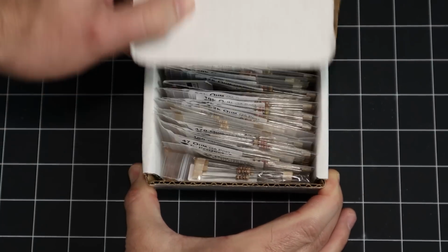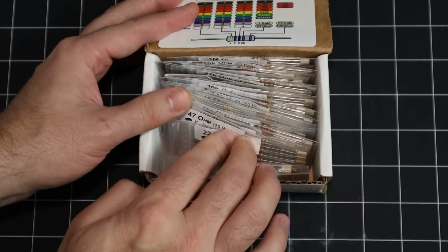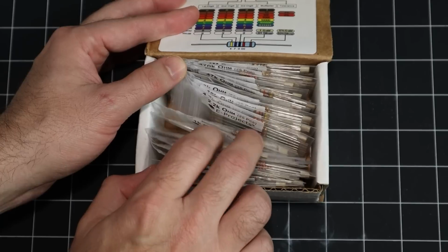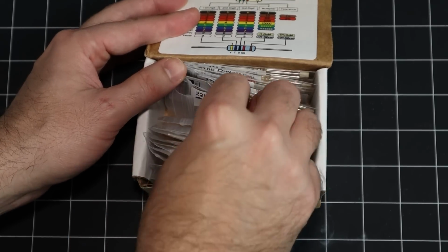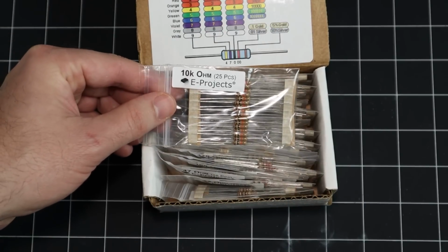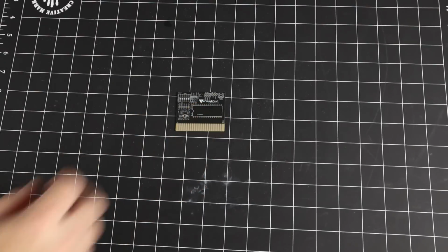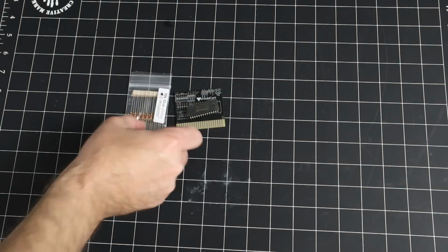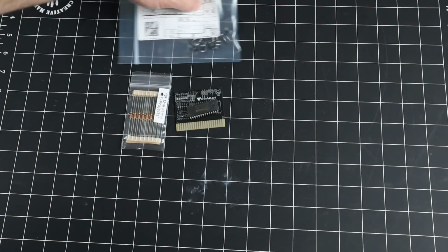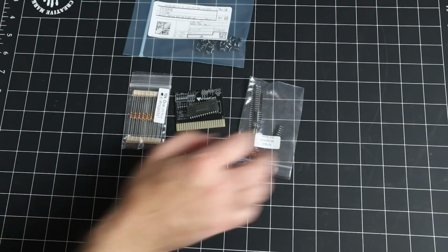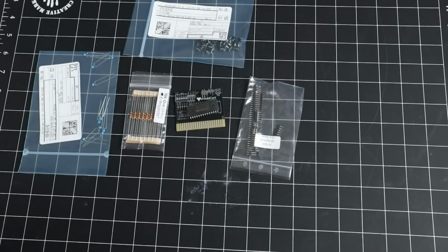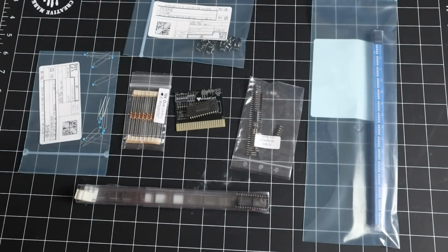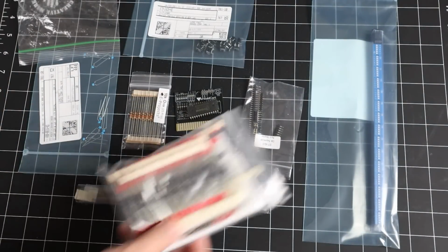To complete the build, you'll need only a handful of parts, about half of which I already had on hand. The rest I ordered from DigiKey. The bill of materials includes the PCB, 64K EEPROM, 10K resistors, reset button, pin headers, a 0.1 microfarad decoupling capacitor, a 5-position dip switch, 28-pin socket, jumpers, and a pair of diodes.